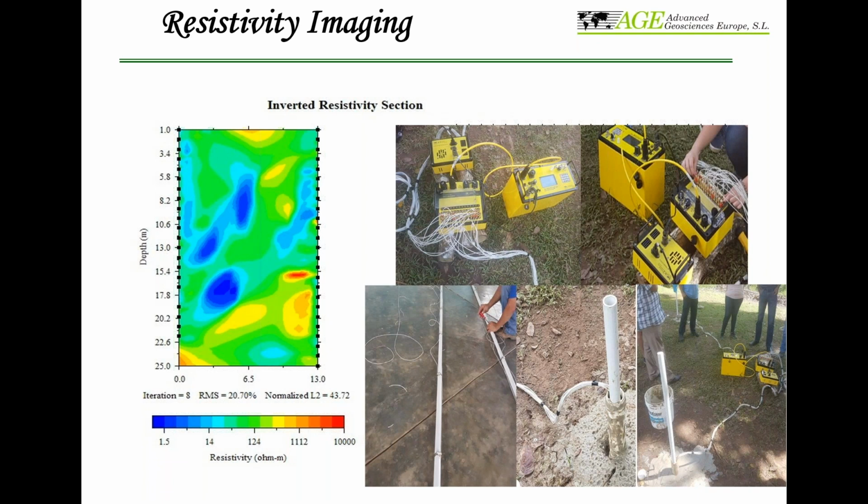If it doesn't saturate with water, you need to fill it with drilling mud. If the drilling mud also escapes, then you need to put in cement. In that case the cable will be permanent in the borehole, so it's not permitted. You're not going to use our expensive borehole cable, spending money and then leaving it in the ground.